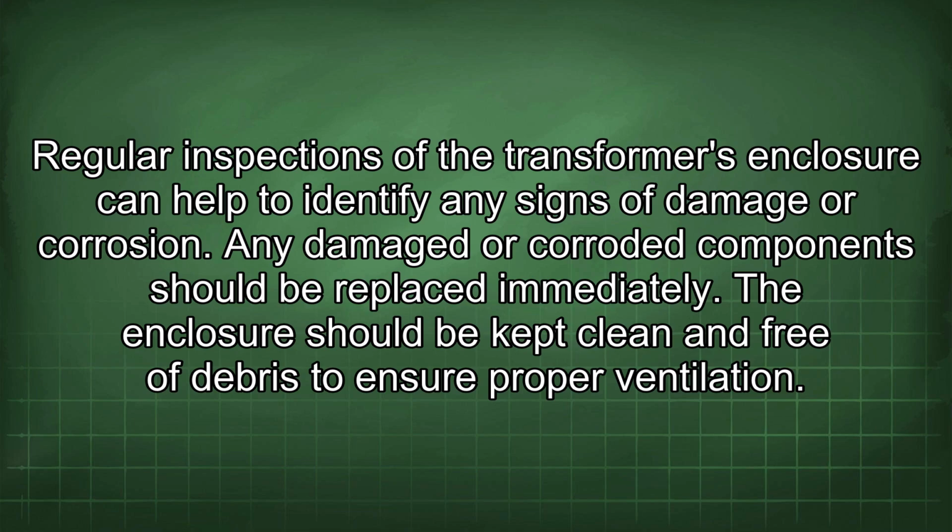Regular inspections of the transformer's enclosure can help to identify any signs of damage or corrosion. Any damaged or corroded component should be replaced immediately. The enclosure should be kept clean and free of debris to ensure proper ventilation.